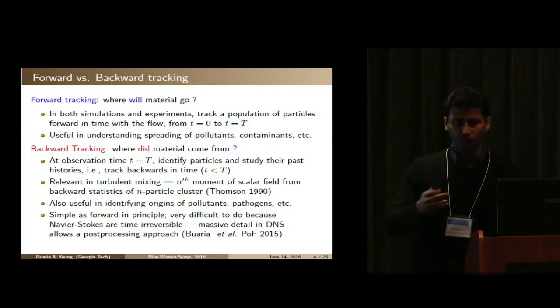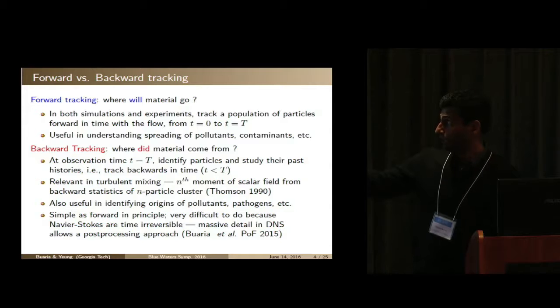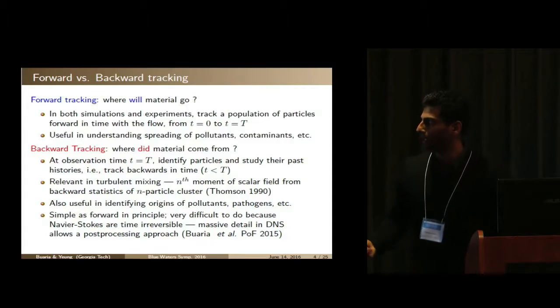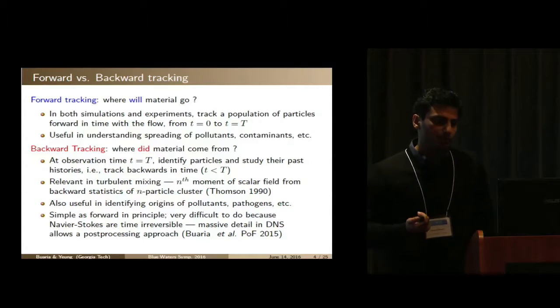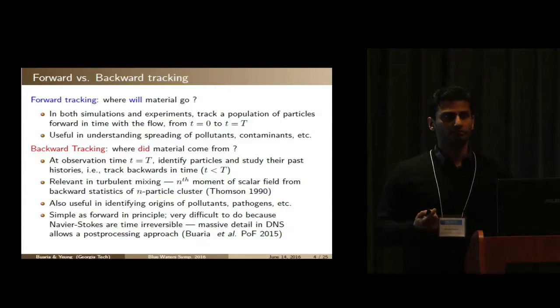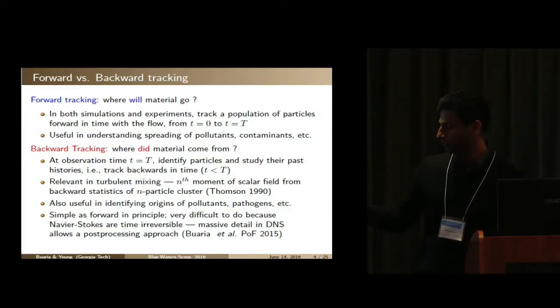The Navier-Stokes still have to be satisfied from t equal to 0 to t equal to capital T. So this approach is very difficult, and it's actually the details provided by DNS that allow a very brute force post-processing approach, which can be found in the following paper.